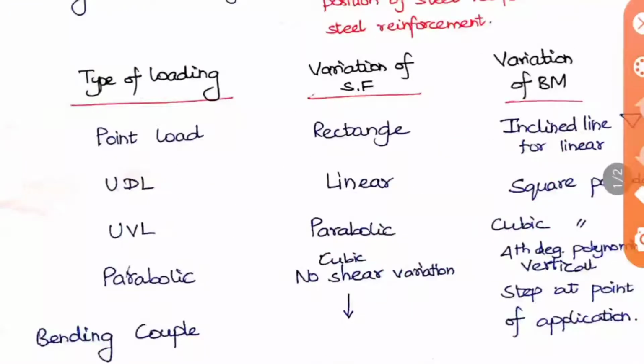And other than that, some points are very important. Now we saw shear force and bending moment. The rate of change of shear force will be equal to the intensity of the loading. So this is very important. That is, the rate of change of shear force will give you the loading. In the same way, the rate of change of bending moment will give you the shear force. Okay, so both these factors are very important.